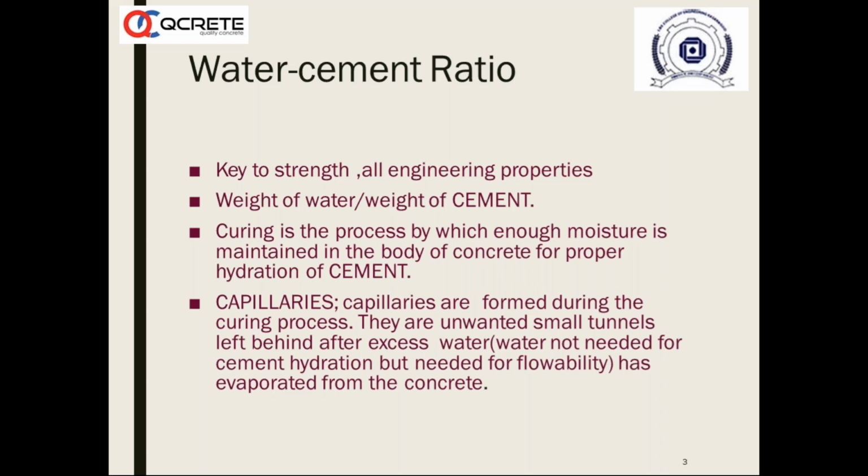Water which is added to the body of concrete goes on evaporating. The evaporation is governed by temperature, humidity, and wind velocity. So these three factors: if the temperature is more, the water evaporation is more. If the humidity is more, water evaporation is less. If the wind velocity is more, water evaporation is more. So based on these three, evaporation is decided.